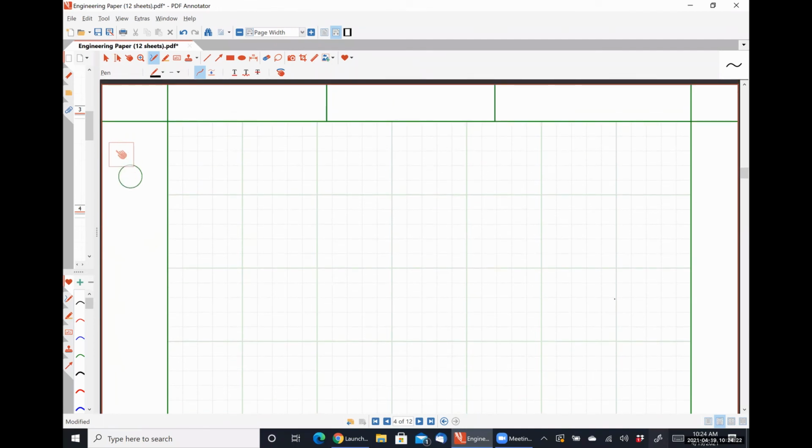All right, so our high frequency model for MOSFETs is going to look something like this guy. We have a gate. We have some capacitance CGS. Hopefully that makes sense to everybody since we've always talked about the gate to source as a parallel plate capacitor. One that may not be as intuitively obvious, we're going to have a capacitance CGD.